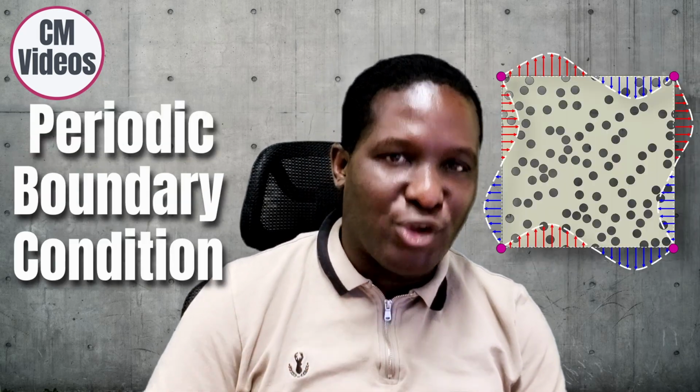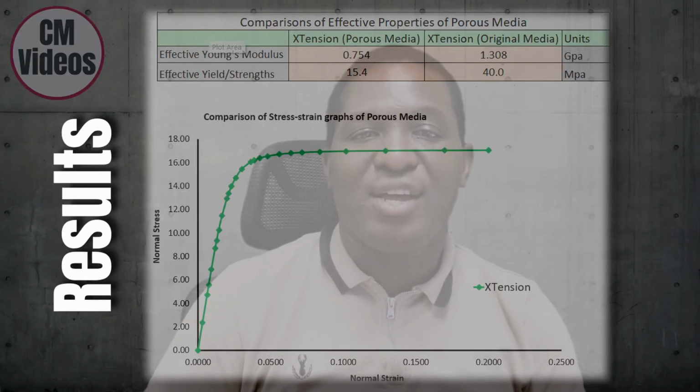So we're going to do two things today together. The first thing is to create a porous media in 2 dimensions, as well as then use periodic boundary condition to impose loading on the structure and then extract the result to see what kind of stress strain data we're going to see. Please do watch to the end because we're going to look at the effect of porosity on the effective properties of a homogeneous material.